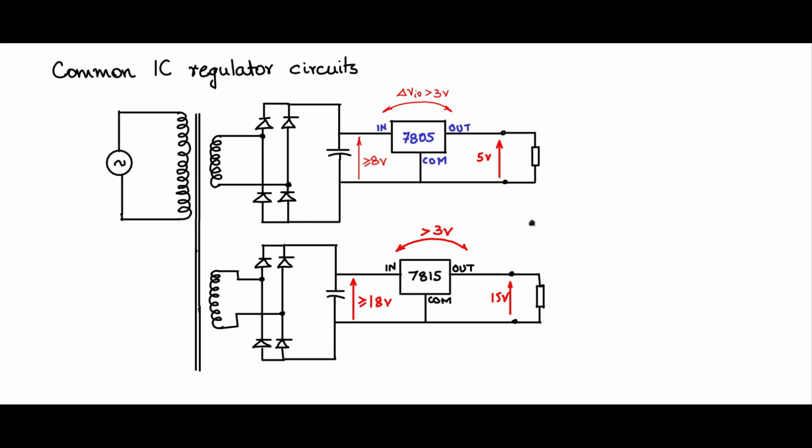Now let us say that we would like to have a dual power supply with a common ground, plus 5 and minus 5 volts. How would you go about doing that? The input side remains the same. You will have a transformer with multiple secondaries, rectifiers, and capacitors. Make some modifications here on the output side. Let me remove this and then put a 7805. I'll set this to 8 volts like this. This will be 5 volts, which means I will replace this by 7805. So both these are giving 5 volt isolated outputs, with no common ground.